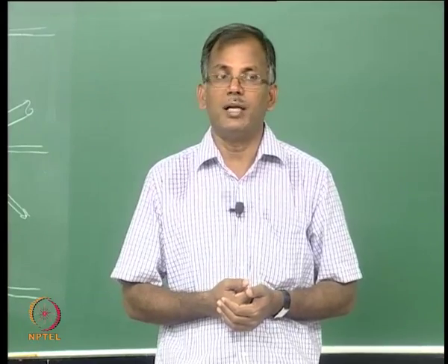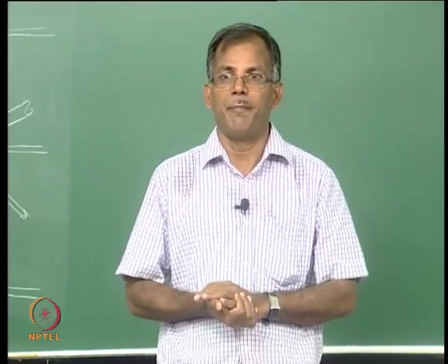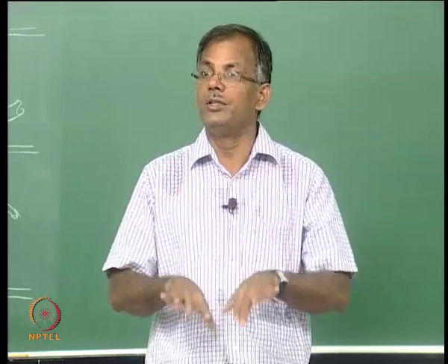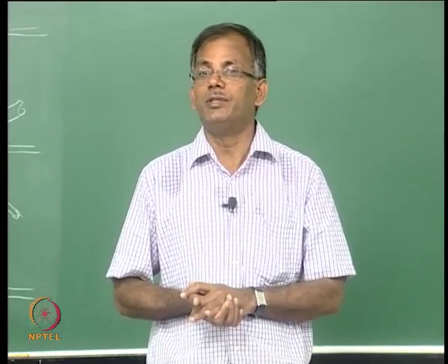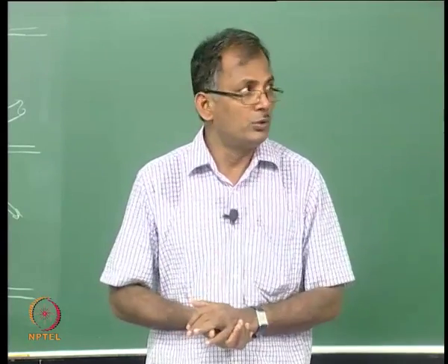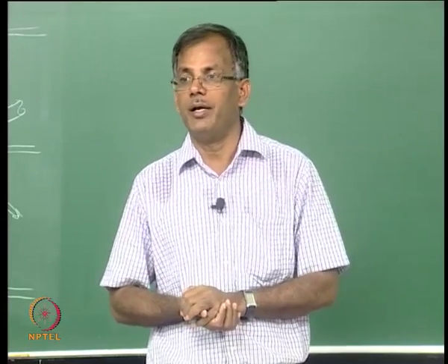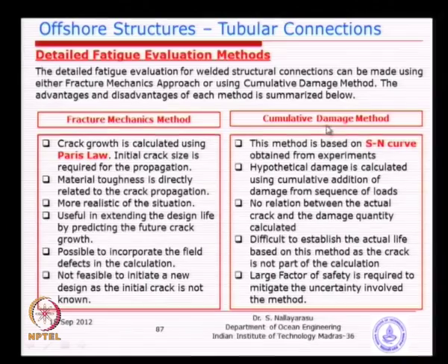A cyclic test does not mean that you can finish the testing in half a day, because you need to apply the number of cycles as per the reality. So, that means it will take a longer time. So, doing too many tests is not a feasible idea. So, what people have done in earlier times, they do a few tests, calibrate with the numerical models and then use those data to extrapolate. So, it is not that every time they do 20 or several tests, because it is involving time and money.